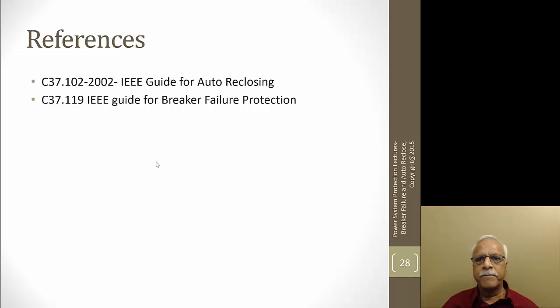And then hopefully you got an idea about breaker failure, where we monitor the current going through the breaker, and when the initiate comes, we look at whether the breaker is closed or the current is still flowing, and take corrective action to open all the breakers adjacent to that particular breaker. And in the restoration schemes, we have different schemes: high speed, time delayed, and sync check. We did cover that this allows the system to be restored automatically without any operator intervention. Thank you.